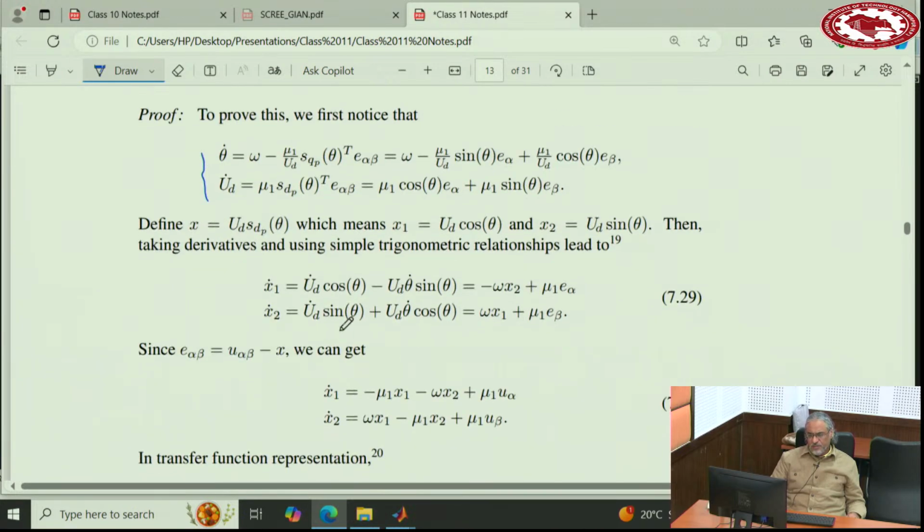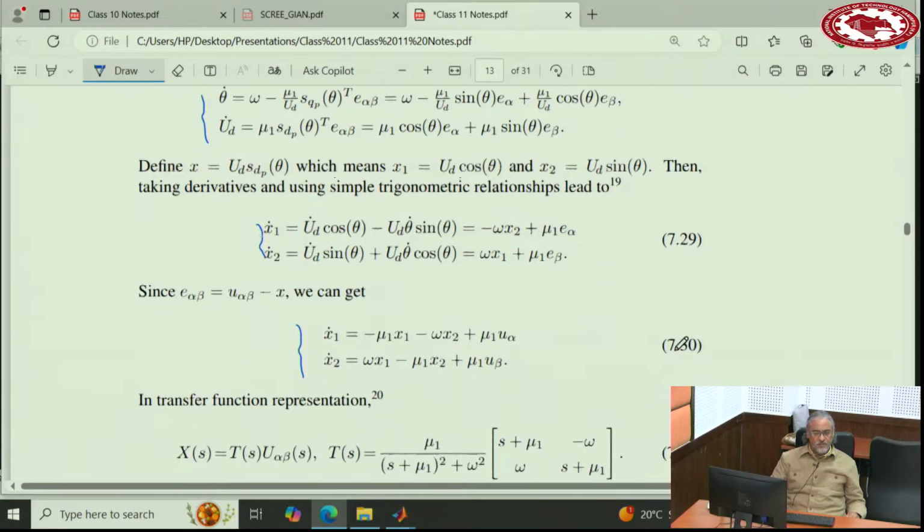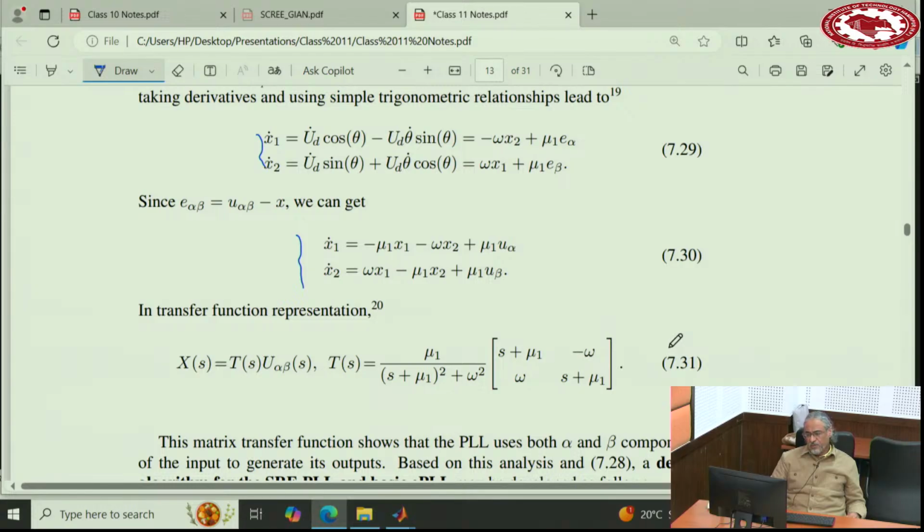You derive the equations and then you make a change of coordinates and eventually you prove that your equations become linear time invariant. And then when they become linear time invariant, you can derive a transfer function for the phase lock loop. Well, this transfer function was never derived before, because remember, it's not based on small signal or anything. We did not do any small signal. Always people in engineering, when there is a nonlinear equation and they want to derive a transfer function, they linearize it.